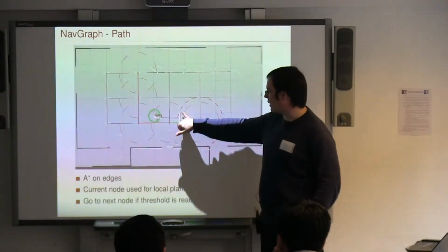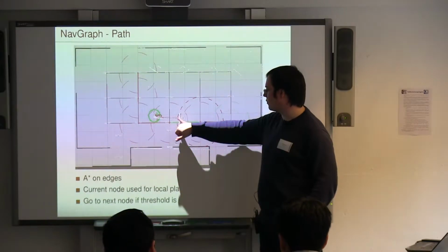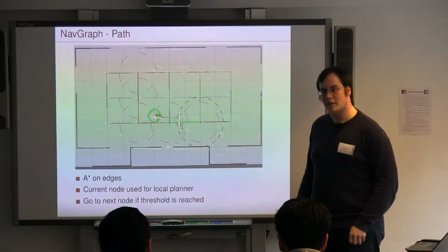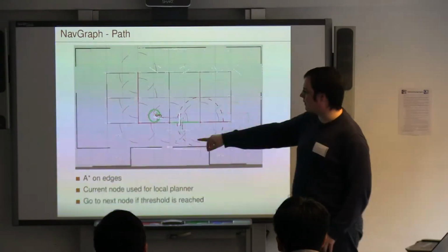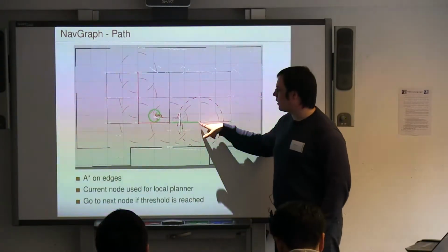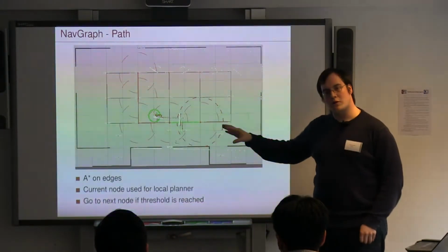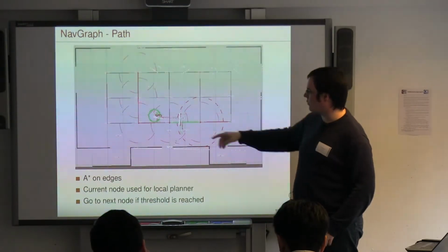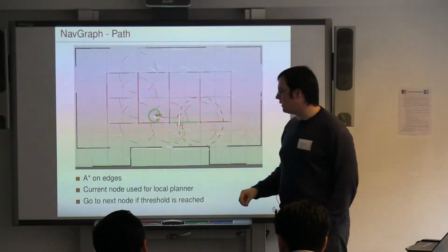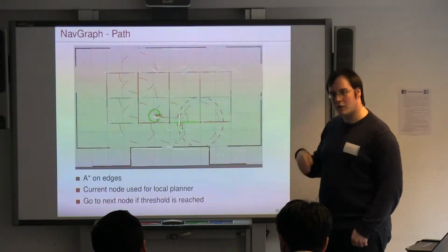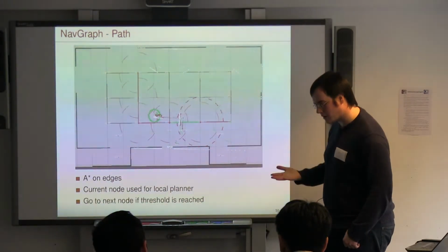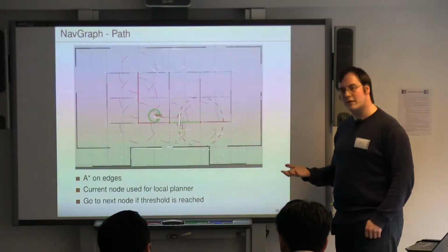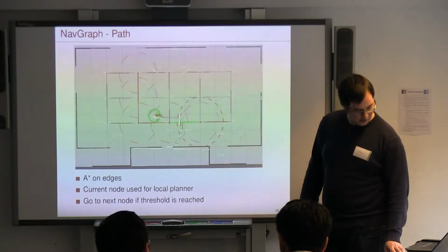But for example, here you can see that the MPS is very close to the border. So that's obstructing the path that the robot wants to take. As I described earlier, with the nav graph, we want to try to have a path that is free of static obstacles, which would be these MPSs. So what we do now is, if we find any MPSs during the exploration, we include them in the graph, and that's what I come to now.